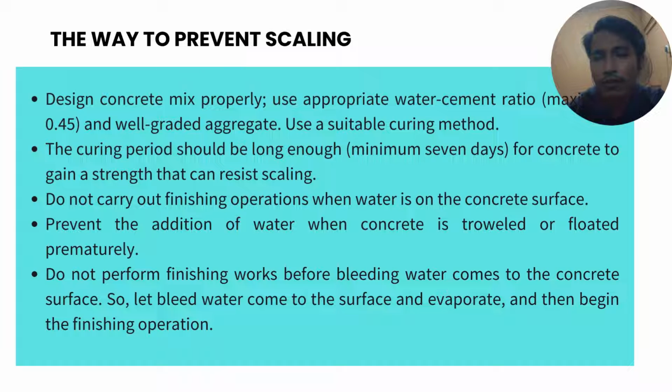Do not carry out finishing operations when water is on the concrete surface. Prevent the addition of water when concrete is troweled or floated prematurely. Do not perform finishing work before bleed water comes to the concrete surface. So, let bleed water come to the surface and evaporate, and then begin the finishing operation.